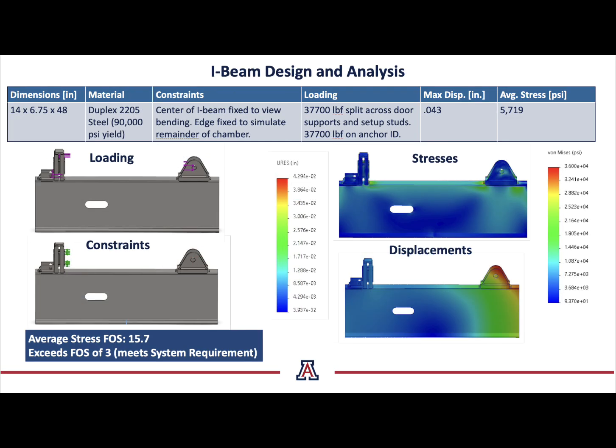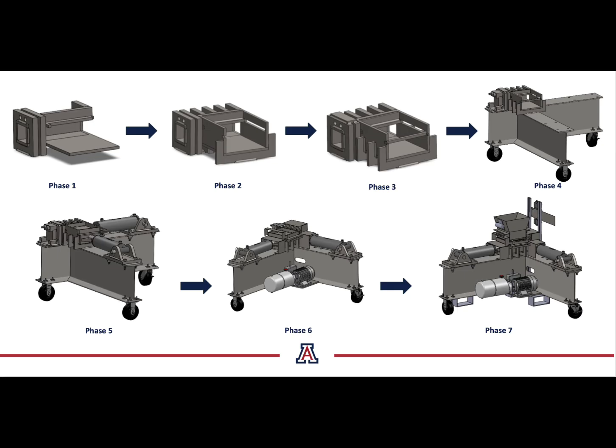Finally, we evaluated the I-beam, which supports the entire system. Even under the full applied loading, the stresses remained well below the yield strength, and the factor of safety was well above the required threshold. Overall, these analyses confirmed that our design is safe, reliable, and capable of performing under the expected operating conditions.